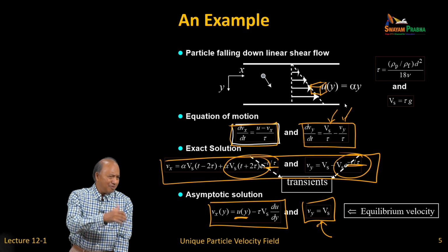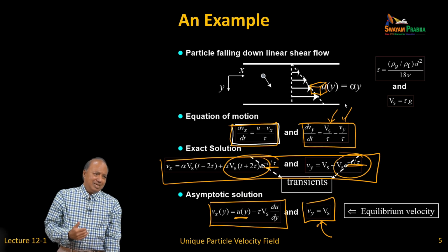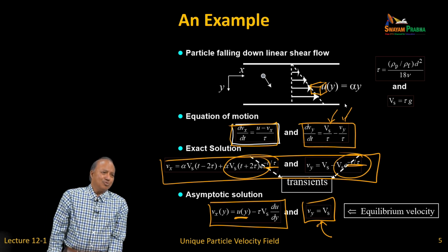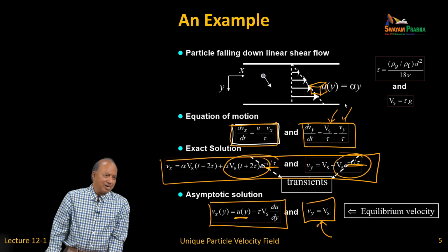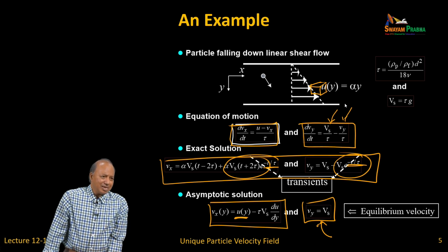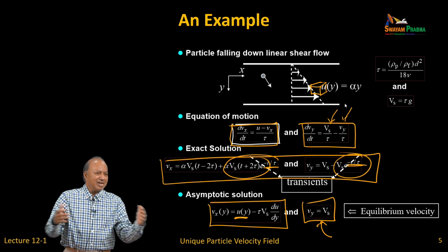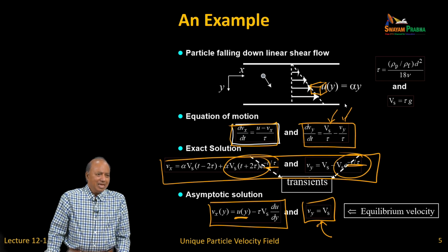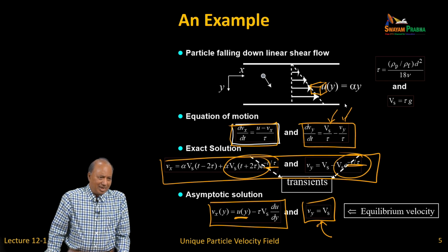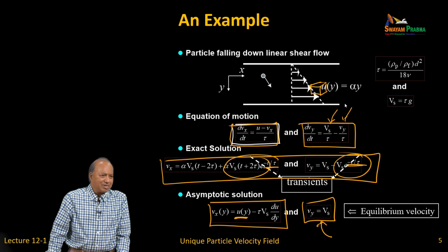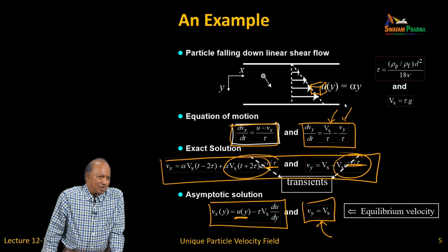Stokes number, if you want my rule of thumb, if Stokes number is like 2, 3, much larger than 1, the Lagrangian method, if you can afford it, will capture the physics a lot more, because you are able to track crossing kind of particle patterns. Okay. Eulerian method is excellent around Stokes number 1, because they don't cross that much, and the Euler method has good merit.